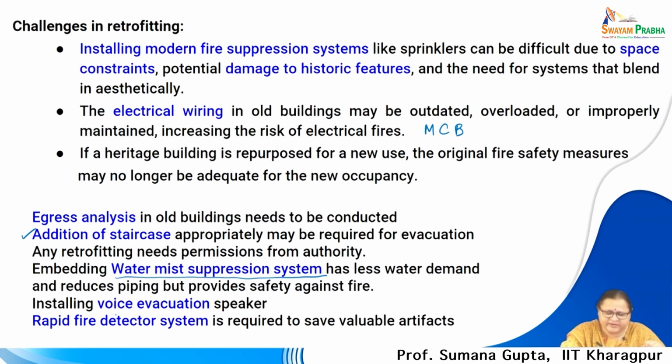Installing voice evacuation system is required, so that immediately in case of a fire or a detection of a fire, the voice evacuation speaker starts speaking, so that the people who are in the heritage building can come out with sufficient amount of time, because egress is the key issue which is a problem in this kind of buildings.